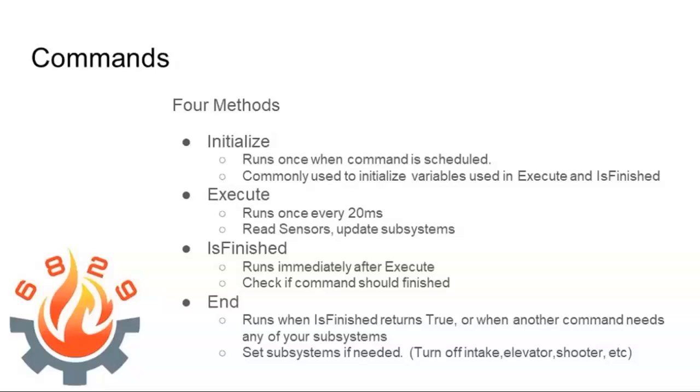Some things you may not want to do that. Maybe end doesn't do anything, right? It depends on how you want the behavior to occur, because if you turn it off and then the next command on the drivetrain turns it on, it may be jerky. So maybe you don't turn it off. Just think about what's going to happen after, and if nothing does happen, what you want the state of all your different subsystems to be.